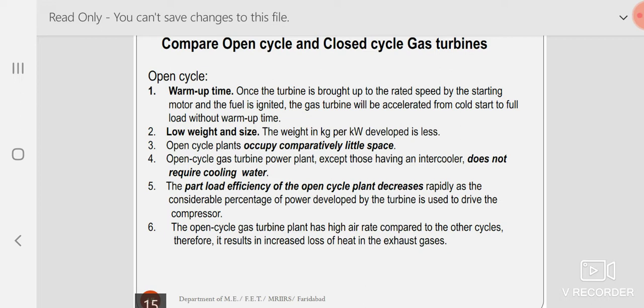Say, for example, on 5th of April, there was a total shutdown of power at 9 pm as per the call by our Prime Minister. What happens as a result? The load decreases tremendously in the power plant, and the power plant may not run. Instead, a gas turbine may be able to take the power, and again that gas turbine power depends on what power load is coming. That power load may be sufficiently less. So the part load means what? A plant meant to run at 100 megawatt is running at 60, 50, 40 megawatt. That is part load.